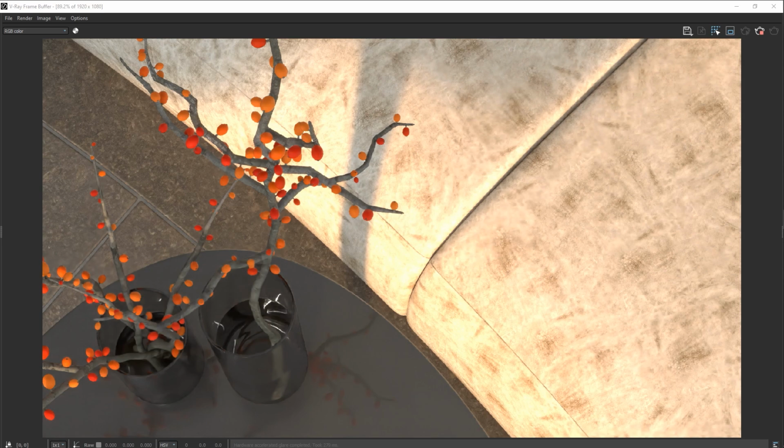Note that you can also use the Tile Blend slider beneath the stochastic tiling to control the amount of edge blending between adjacent tiles. That said, just simply enabling the stochastic tiling has already given us a much more authentic looking result without any need to overlay multiple textures or spend time tweaking parameters.